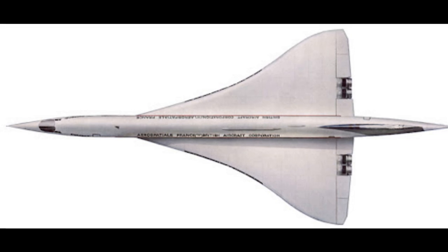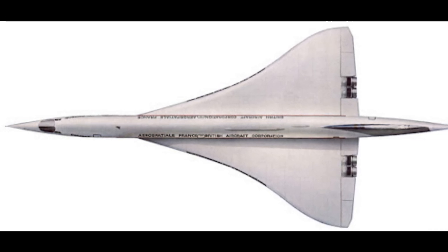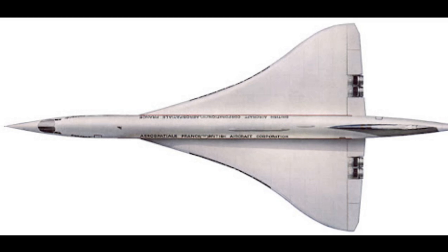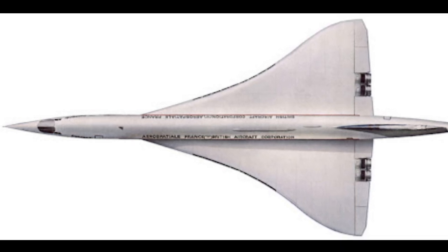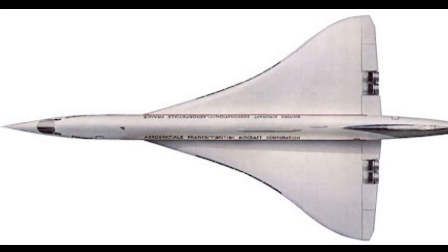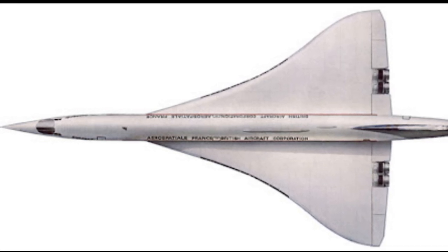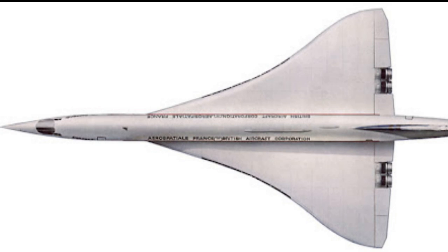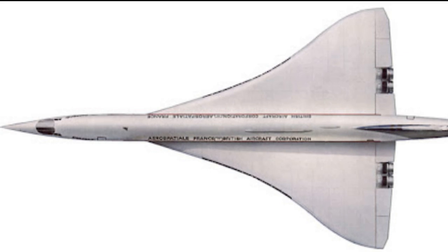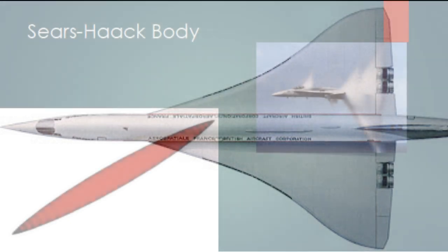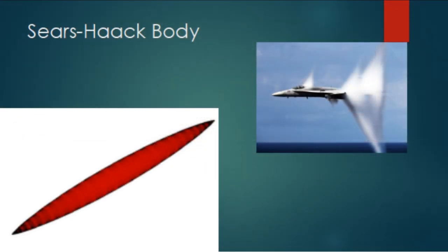When applying the transonic area rule, the condition that the plane defining the cross-section meets the longitudinal axis at the Mach angle μ no longer prescribes a unique plane for μ other than the 90 degrees given by the M equals 1 part of the equation given earlier. The correct procedure is to average over all possible orientations of the intersecting plane.